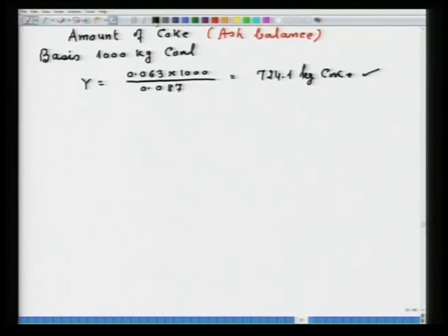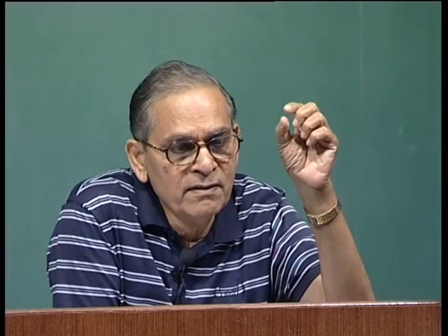Now, next you have to calculate the coke oven gas produced. In order to calculate the gas which is produced, again you have to select an element which can be seen in the balancing and which is not lost anywhere. You select hydrogen, it can be lost. You select oxygen, it can be lost here and there, it can combine and so on. So, here if you see the carbon, if you do the carbon balance, if you charge x kg of carbon, then x kg of carbon should be available to you in the product and byproduct.